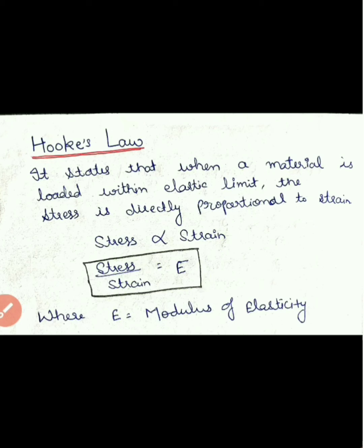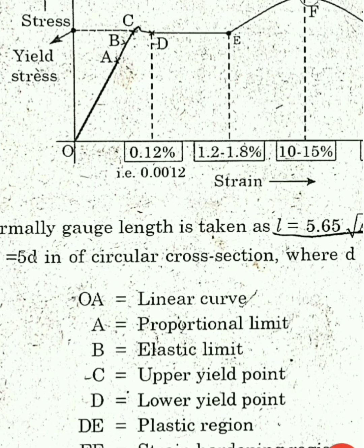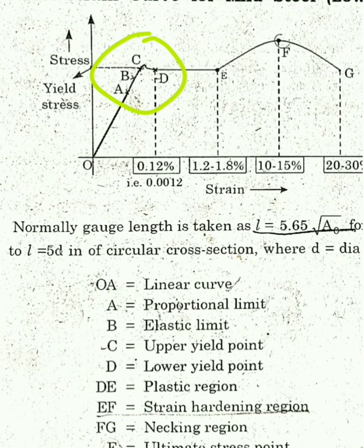Now come to the figure. So from the curve we can see that Hooke's law is applicable from O to A, where A is your proportional limit. Focus on AD now. Here strain increases more rapidly as compared to stress. This is your stress, this is your strain.